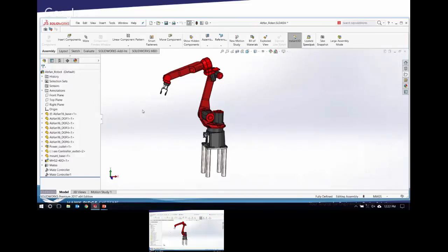Yeah, I think it's pretty universal. It's just something that I think SolidWorks has kind of struggled with. There was an improvement in the last couple of years, I think maybe it was in 2015, in regard to angle mates, which is that now you can define a reference for the angle, which should prevent angle mates from flipping around in different orientations.